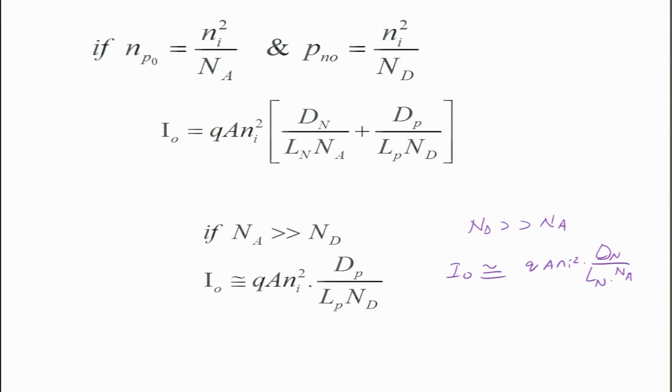So basically this is the expression for current that you get. When you plot it now, this is the forward current which has an e to the power q Va by kT minus 1 dependence, and this is basically the minus I0 you get in the reverse bias.